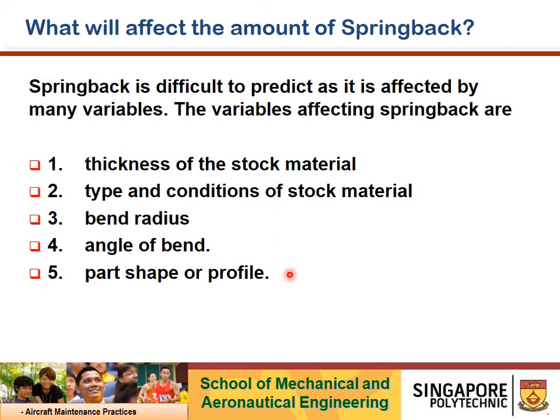All right. So the difficult part about bending sheet metal is the amount of spring back effect. It's not that easy, especially as we have various series of aluminum alloy: 2024, 7075, 5056, or even pure aluminum 1100. I would say sheet metal bending is a bit of art, judgment, accuracy, and skill.